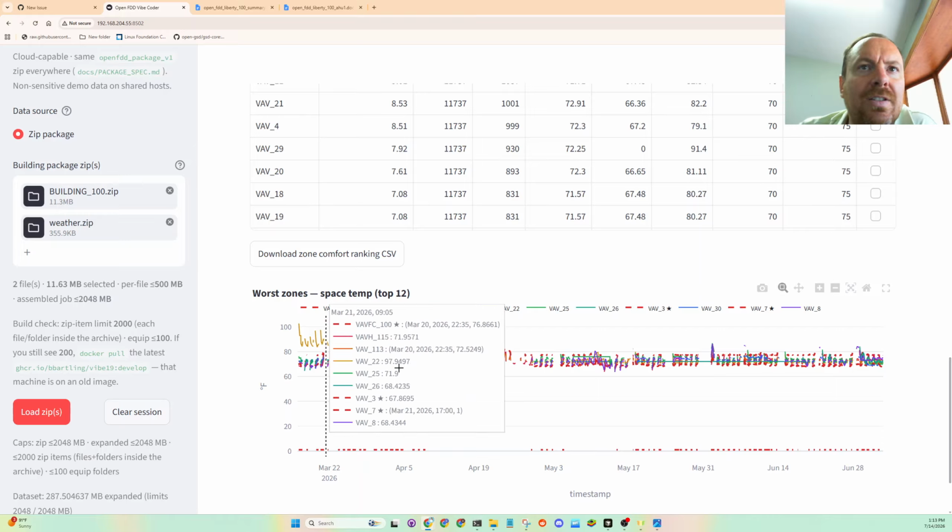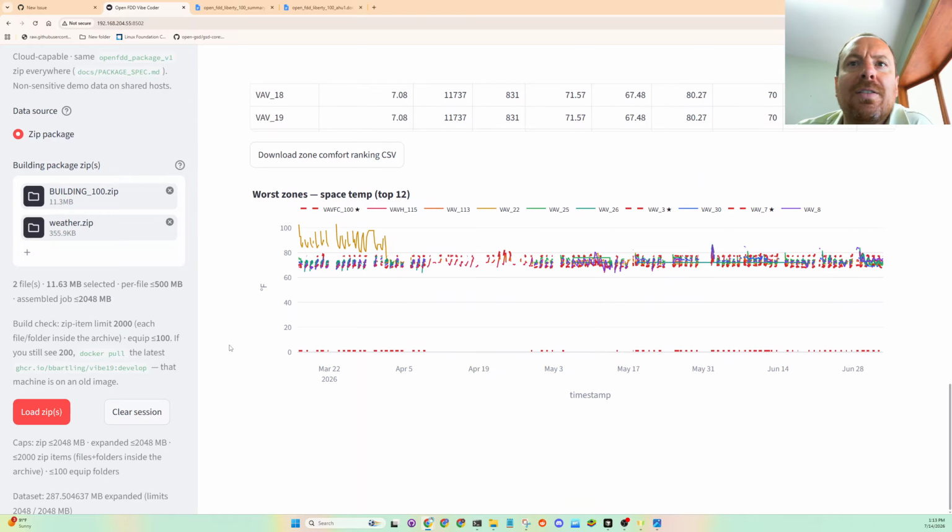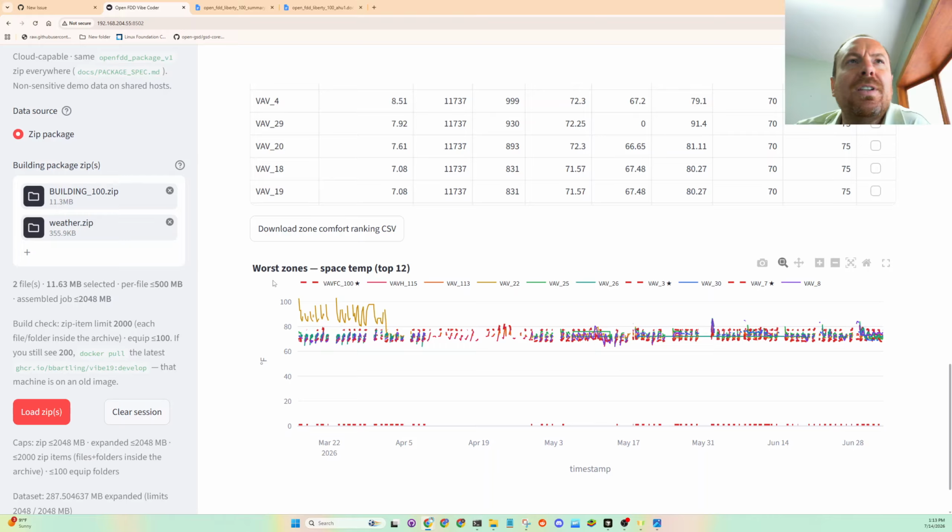Okay, so this is filtered for when the fan systems are running. Something I also have to get is the feeds relationship from the client, on which air handling units are feeding which VAV box, and then we could even do a further dive into VAV box level components. It would be really interesting if we could diagnose what's causing some of these problems in the mechanical system.